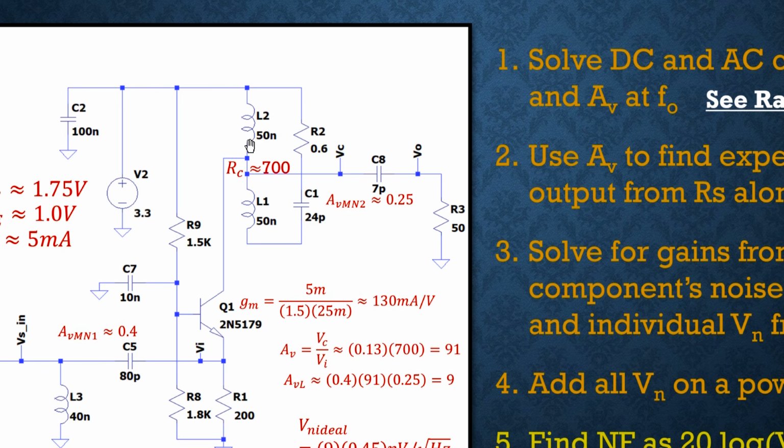In any case, if you know the reactance of either the inductor, which is the net series here, or the capacitor, here it's 62.8 ohms, 63 ohms. If you know that and you multiply it by the Q, then you get the effective parallel resistance from this node here to this node, which is AC ground. And that works out to be about 6,000 ohms.